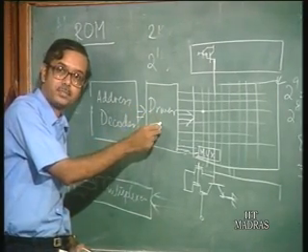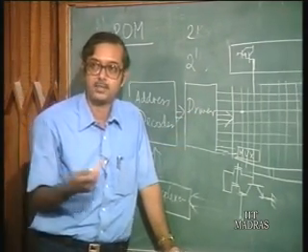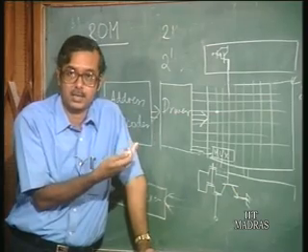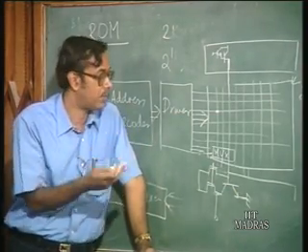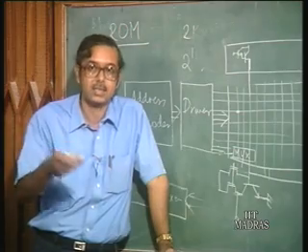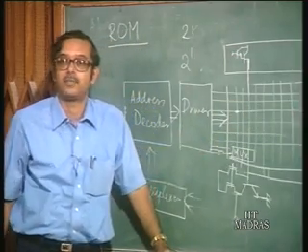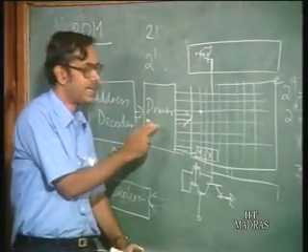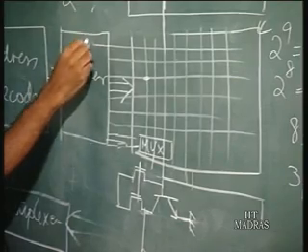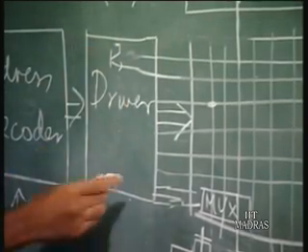We have already seen that BiCMOS is going to be very good as a driver, because it can drive large capacitances since you are using the bipolar transistor. When you compare CMOS with BiCMOS, the variation of delay with large capacitance is much less. So, it is capable of driving large capacitances, because the word line capacitances are quite large. So, here again you use bipolar transistors in the driver stages. Here the output is actually from bipolar transistors.